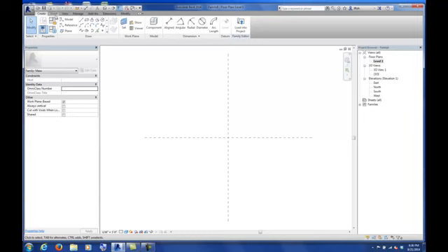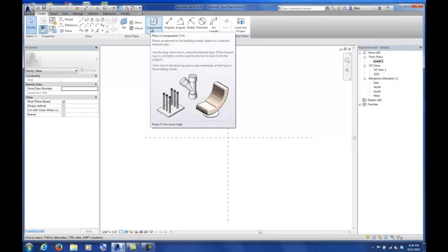But up here at the very top, if you look at Create as your menu heading, this is where you've got all your draw commands. And these draw commands operate exactly like AutoCAD or any other CAD program that you've been in. And I think everybody here had said they had some kind of CAD experience. The trick here is there are no real true shortcuts in Revit where you can type in like you're probably used to in AutoCAD.